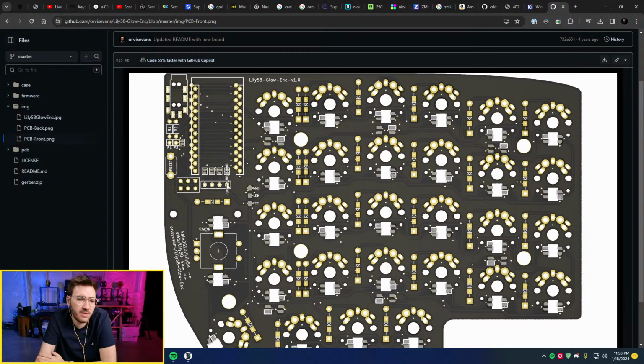So you don't need a power switch on a wired or a wireless board. You can use Deep Sleep, which is a ZMK feature. That's what I use on my wireless ones. My cases I sell for the corne actually don't have switch cutouts either, because Deep Sleep just mostly works. But you can also add a locking layer. You don't need a power switch. It's nice to have, but you don't need it.